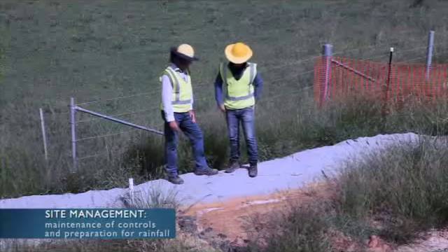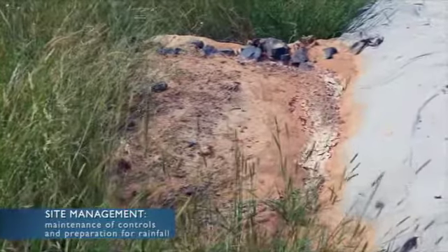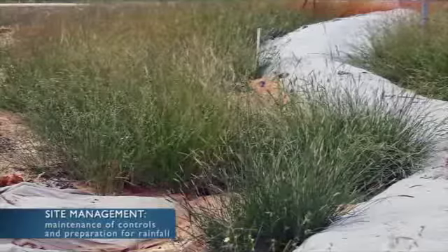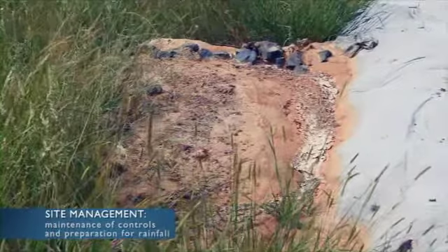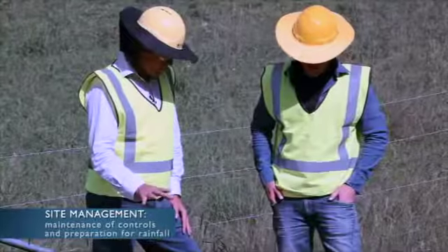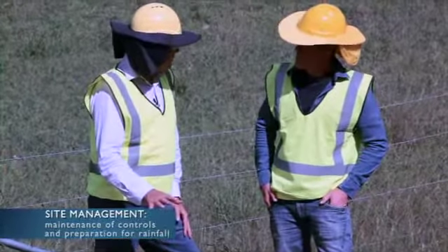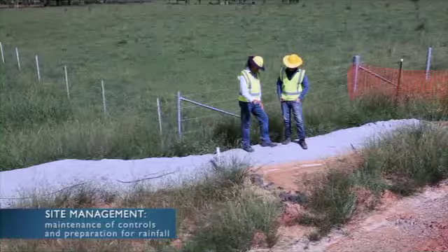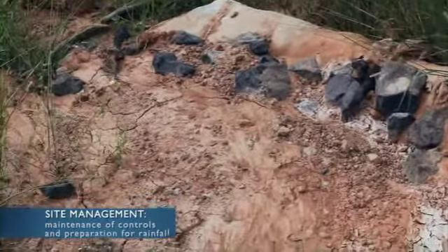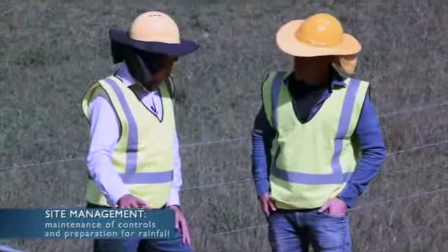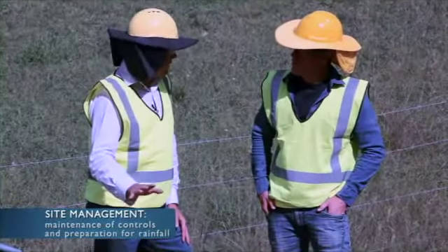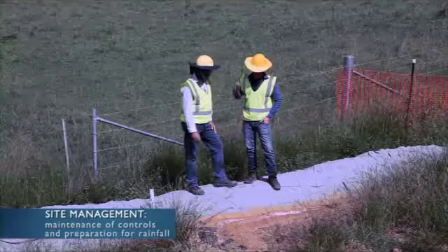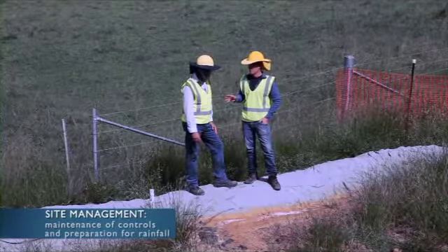What are we looking at here? Okay, Pete, well this is a small check dam, and as you can see it's in a series of small check dams here. Two things I'd like to point out here. Firstly, just have a look at how much sediment that's been captured. They actually do a significant job in terms of preventing this stuff going off site. Second thing is, obviously after the last rainfall event, it's still full of sediment, so it's certainly not going to do the same job next time. So what we need to do is get in and dig that out, and then we've got the control ready to go for the next rainfall event. Yeah, so it's not only monitoring, it's maintaining all those control points.